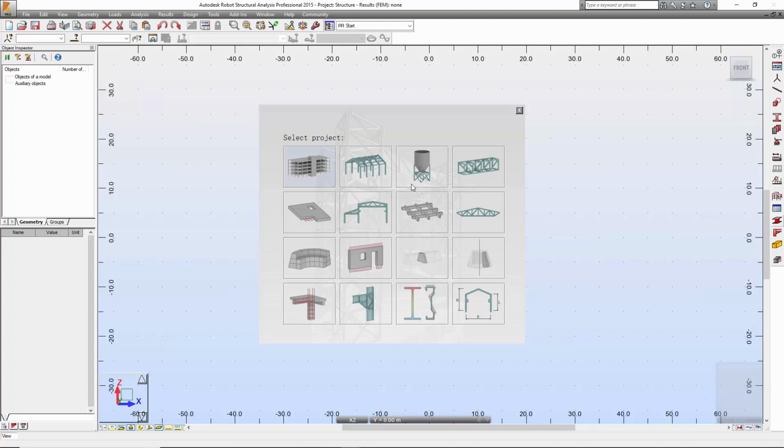So that's why in here we need to use the frame 3D design to create these structures. So don't use this one, okay? Don't use the truss, otherwise it's not going to work, because later on you can apply the beam or column properties to the structure we're going to add on. So let's use this one, the frame 3D design.